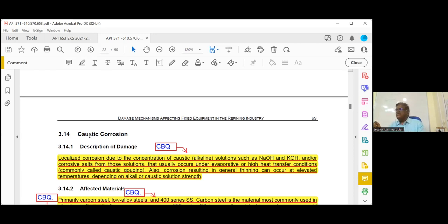Now, very, very important, which material is resistant to caustic, both to corrosion and stress corrosion cracking? It is nickel. Nickel based alloys are always resistant to caustic. Okay. So what are the nickel based alloys? I told you nickel content should be more than 30%. How will you identify the nickel based alloys? Alloy 400, alloy, a 3-digit number, 600. So generally alloy 400, alloy 600, and other nickel based alloys are highly resistant.